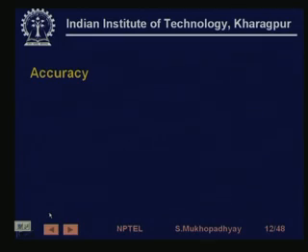Next, let us talk about perhaps the most important parameter, called accuracy. If you see instrument specifications, they will generally be written as accurate to within x% of either reading or span. Sometimes they say reading, sometimes they say span. In fact, sometimes they also mention constant values, that is, accurate within plus minus 1 degree centigrade. When it is a constant value, since the span is a constant quantity, you can always express it as a percentage of span also.